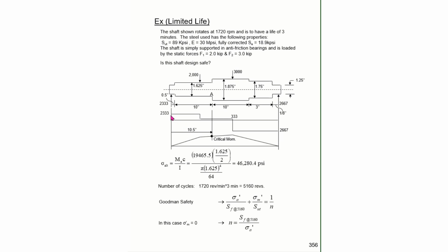Now we have a shear and moment diagram that's given as shown here as our shear, and then our bending moment diagram is given here. Now I've already computed the critical stresses, and the critical stress location is this location A. Note that you would need to determine this location by computing the stress here at point A, as well as here at this peak value.